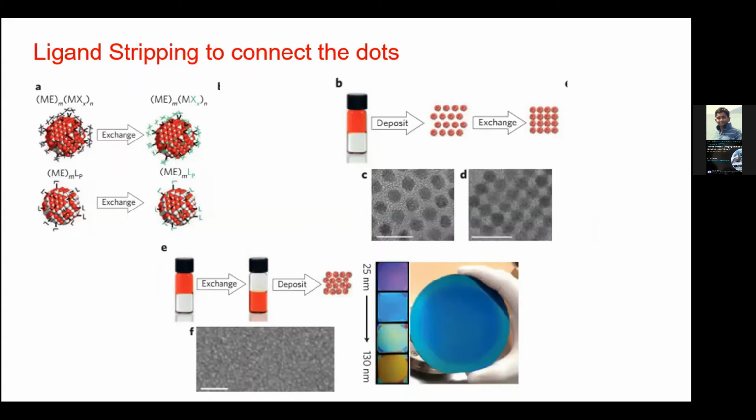The electron or hole goes through by hopping. In the last talk, someone asked me how the charge goes through this. It goes through hopping. This hopping means, if you apply a bias, it generates an electron or hole, depending on your nanocrystal's property. The electron goes from here to there, and there to there. It's called the nearest neighbor hopping model.